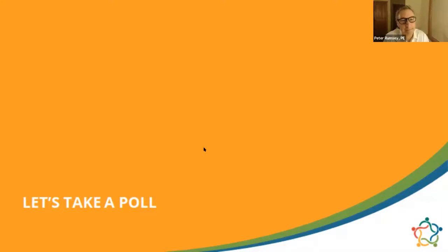It's fine. Right. I think let's end the poll here, and I am going to share the results now. Okay, here are the results, Peter. Great. So here's an interesting distribution, everywhere from less than 200 to more than 800. So the higher number means a smaller cooling system, right? 800 square feet per ton means there's more square feet for every ton of refrigeration.